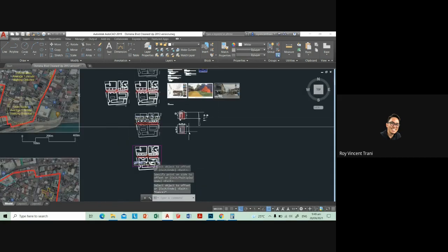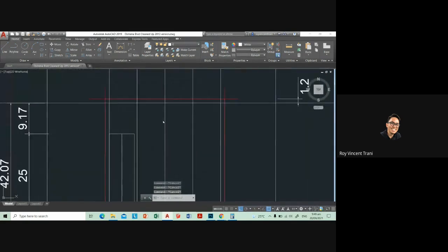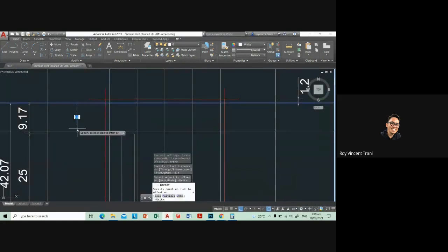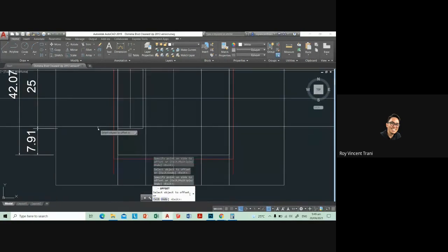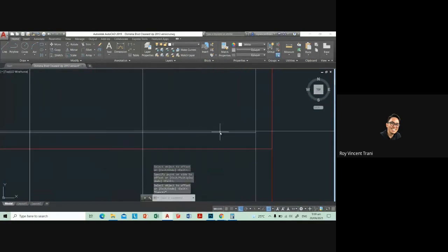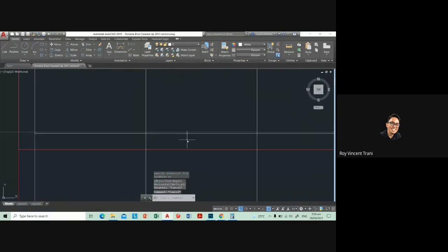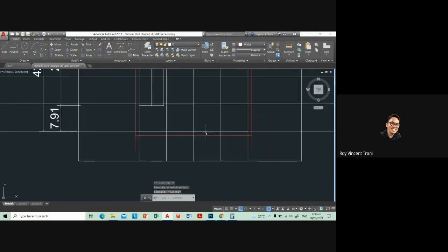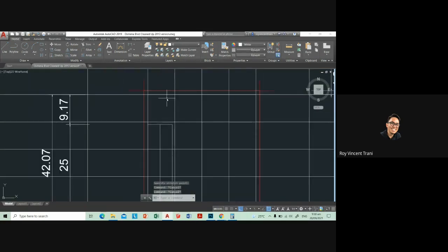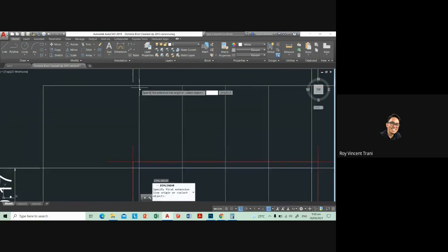8.4. And there's a little bit missing, about 0.1. So maybe I can reduce the frontage by 0.1 or something like that. And then let's say a column that is 600 by 600 is actually very small, especially if your spans are like 8 meters.